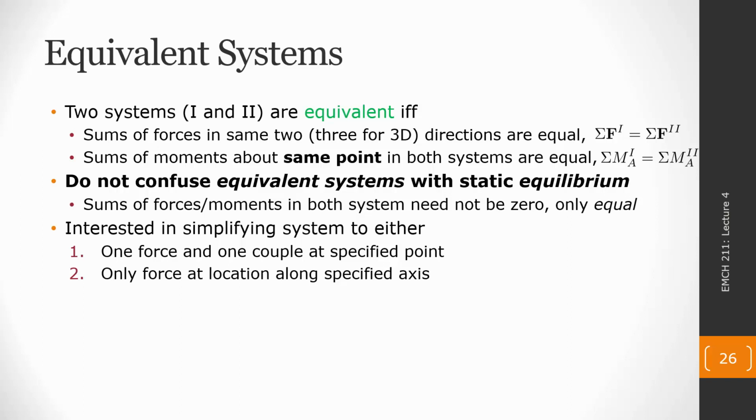And what we're going to find again is that externally, I keep stressing that because internally is a different story, but externally, the systems are going to be identical. Again, this is checked by summing the forces, summing the moments, and seeing that they are equivalent. So why would something like this be useful to us? Why is the ability to simplify our system to a force and a couple, or one force, going to be useful?